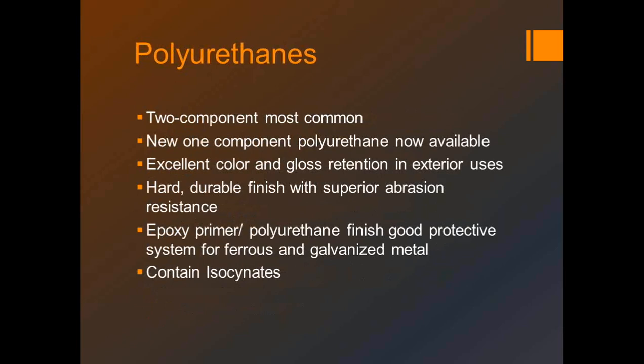The firm I work for in Cincinnati did most of the work for the zoo that has well over 1 million visitors every year. And on the areas where we wanted a color handrail as opposed to stainless steel, I used polyurethane top coat over a high build epoxy first coat, and they wear wonderfully because even the best conventional paint is going to get pinhole rusting in just a few years.